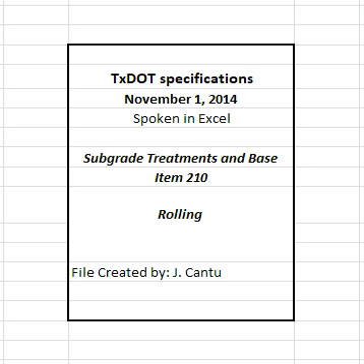Stop vibration before the motion of the roller stops, and thoroughly moisten the drum with water or approved asphalt release agent. 2.3.1 Drum, Type A. Furnish a roller with a static weight less than 6 tons and a vibratory drum. 2.3.2 Drum, Type B. Furnish a roller with a minimum static weight of 6 tons and a vibratory drum. 2.3.3 Drum, Type C. Furnish a roller as shown on the plans.